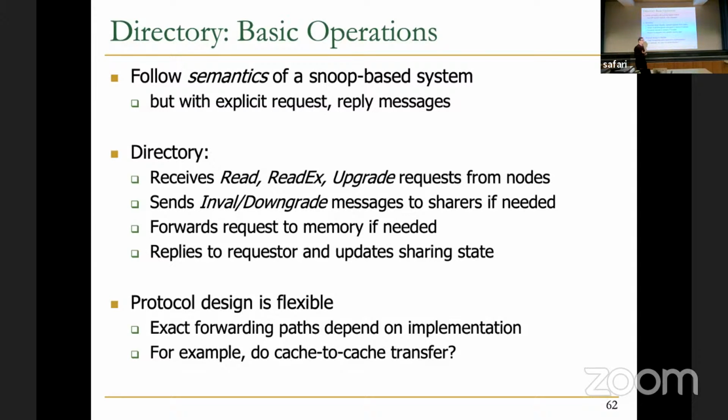These systems were big multiprocessors of their time, in the 1990s, and they basically implement directory-based protocols. And a lot of these directory-based protocols are actually programs running in the memory controller. They call it the home engine, for example, or directory engine, something like that. Essentially, you can have microprograms running in the directory to decide what to do. And these can get updated also while the system is running, potentially, right? So essentially, in the field, you can actually change the protocol.